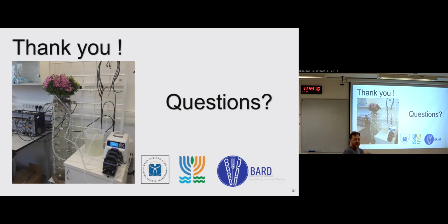Yeah, not here, not in this model. Of course, we can consider evaporation or even Darcian fluxes, and not go with this coarse approach, and go, for example, for modeling with the Richards equation with a sink term inside. Yeah. This is what we assume.